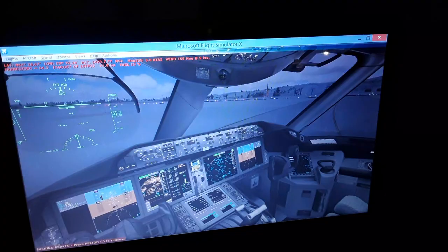also the mean aerodynamic chord position, the angle of stall, and the horizontal trim stabilizer for takeoff position 4.35 degrees. We're gonna use 15 degrees of flaps for takeoff for this runway. So we have the runway 14 in the Zurich International Airport, Switzerland. We're gonna use the LSZH localizer also, both for takeoff and for landing. So we're gonna select the runway slope.